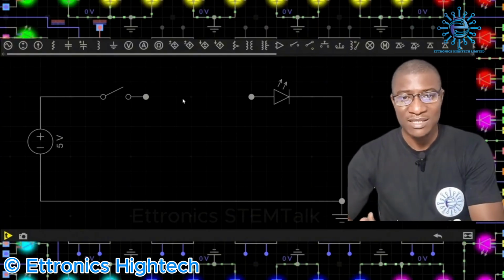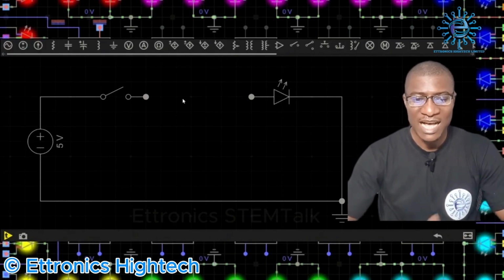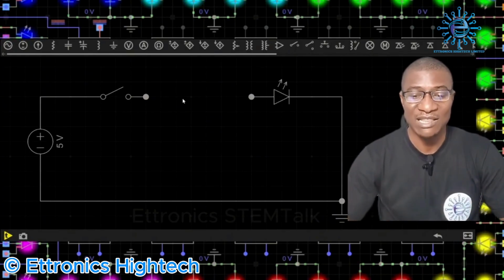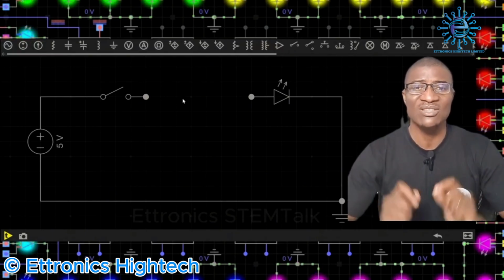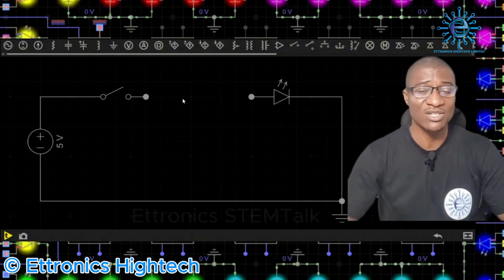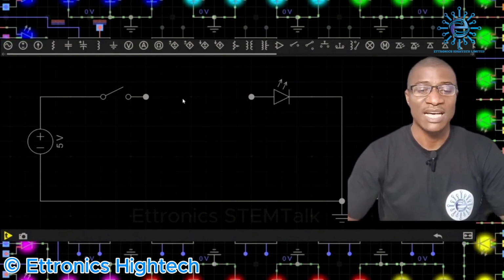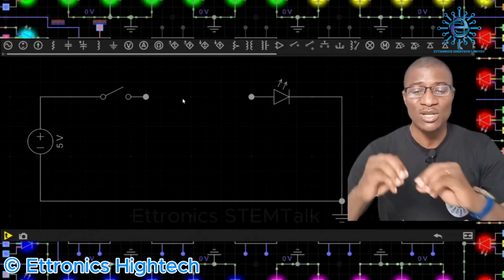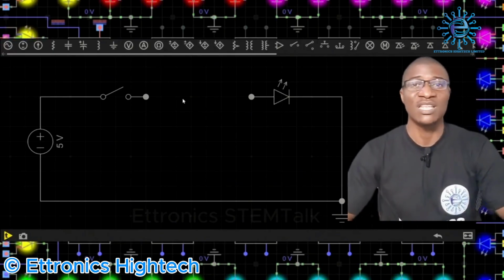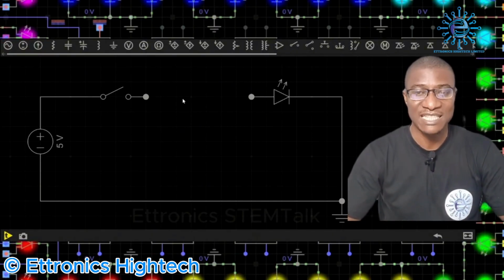Now, it happened that sometimes when I made my connection, my LEDs would burn, and I couldn't figure out what the problem was. Well, I've come to know that the reason why I sacrificed a lot of LEDs then was because of my limited knowledge of the various electronic components. I never knew what is called a resistor, that a resistor will help reduce the rate of current flow in my circuit. Now I know that there's what we call a current limiting resistor that you must connect to your LED in series to help you reduce the current flow to that LED, to avoid having that LED burn out.